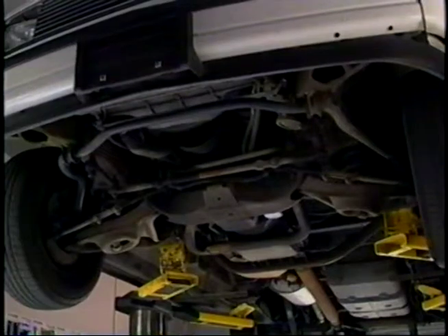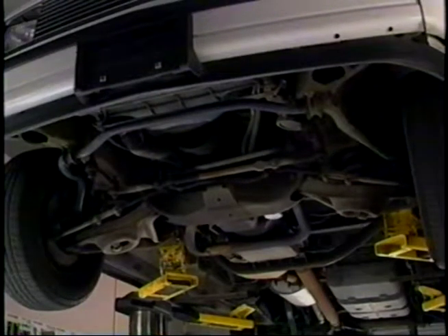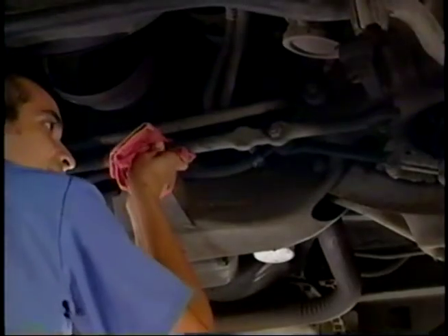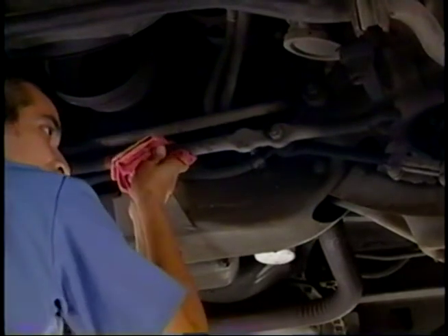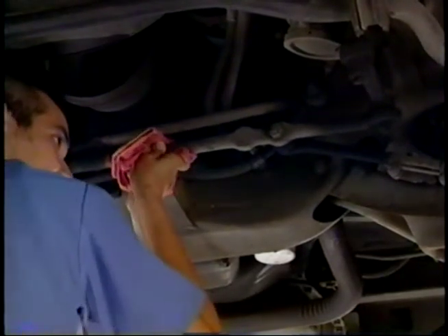The parts of the steering linkage used on traditional steering gear systems are the idler arm, the intermediate shaft or center link, and the tie rods. Wear in any of these parts will cause excessive free play, not to mention excessive or abnormal tire wear, vibrations, or loose steering. Diagnosing these parts is as simple as pushing on them with your hand to check for excessive movement. Always replace worn or damaged parts.